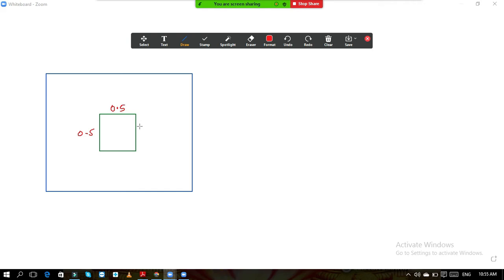But here in one-way shear, we will consider the strips from two sides only. One strip is along X, another is along Y. So how to do that? See over here. From this face of the column, that is the vertical face of the column, I will draw the critical section at a distance D, which is somewhere here.